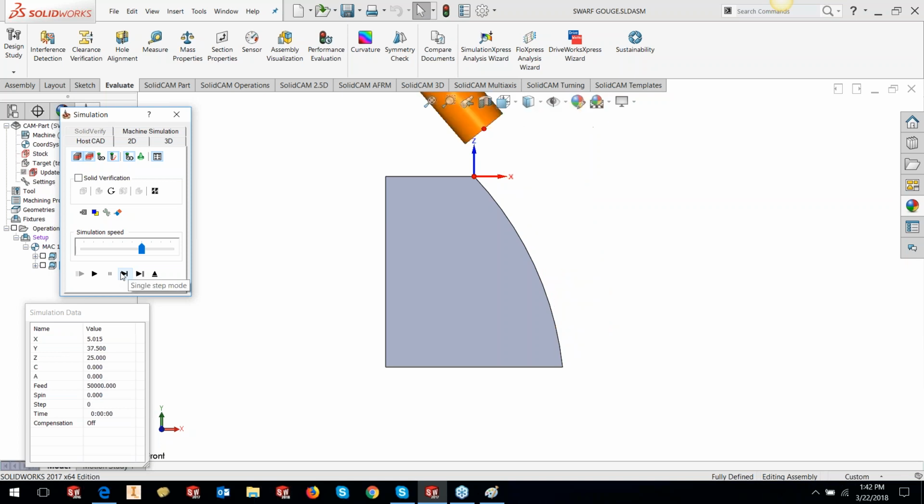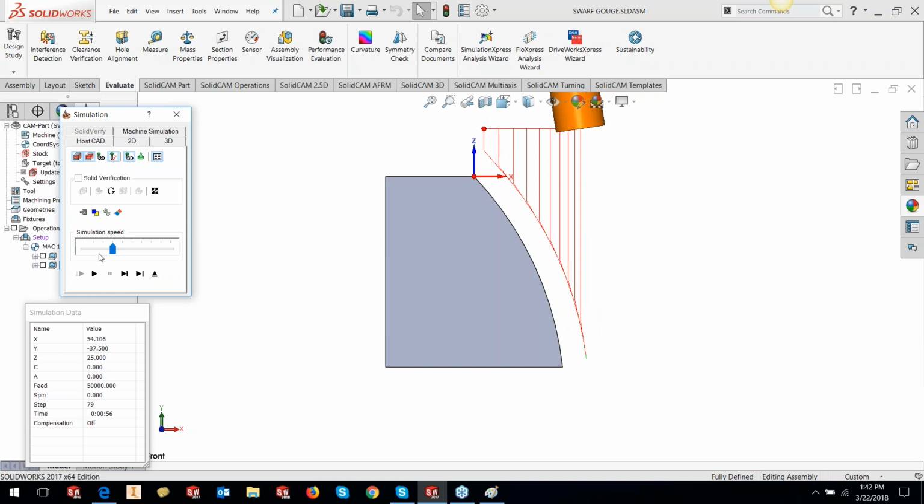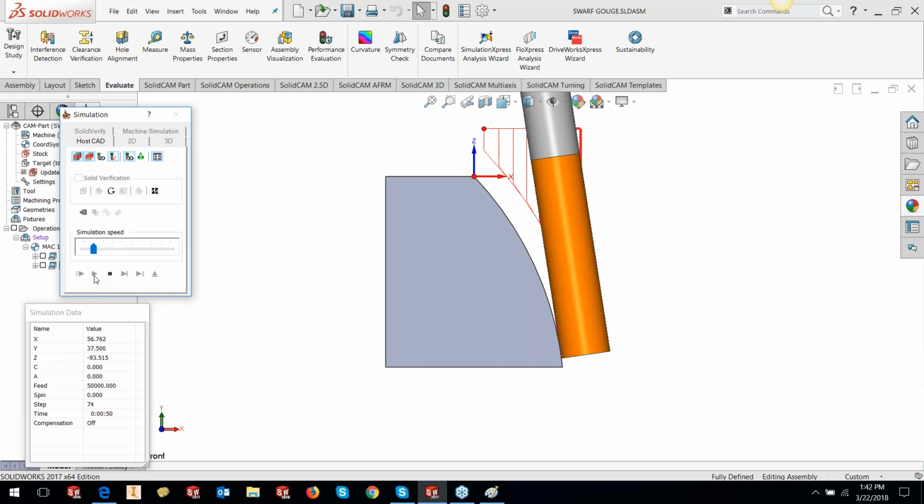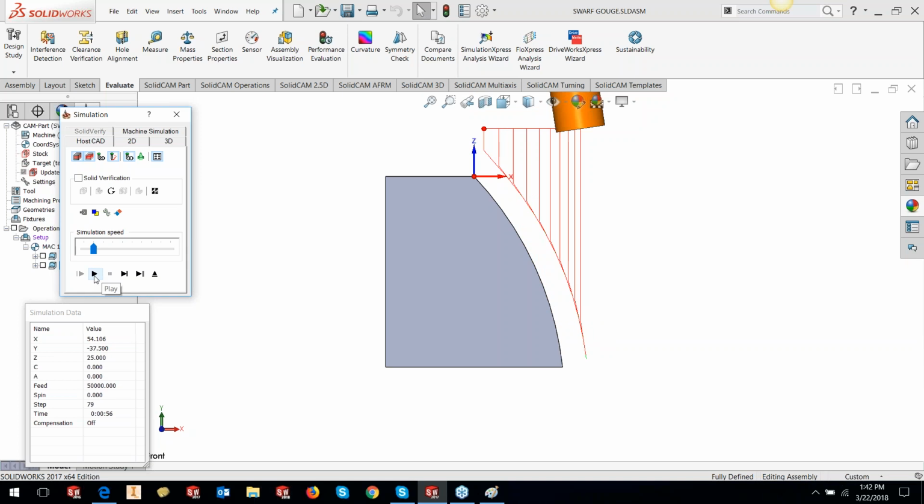So you can have multiple passes on curved surfaces. Very important in some cases where people would like to do roughing with large cutters, they can use this method of doing large cuts and follow the tool axis based on the surface topology, and then once the roughing is done, you'll get a lot of steps.